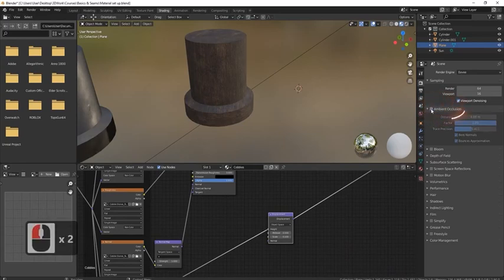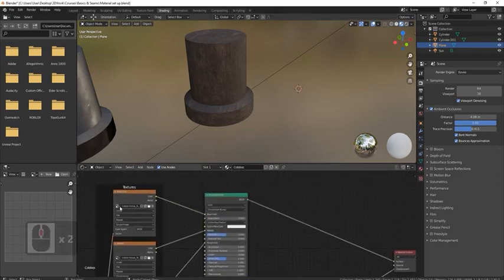When you click this on, you can see already that we really get much more shading on here, much more realism and things like that. Now, as I said, you can get textures where they have ambient occlusion already built in, but I find actually doing it this way generally gives you a better result. Now, the other thing you can do is you can mess around with the ambient occlusion and really bring it up or down, mess around with factors and things like that, and really get kind of the shadows that you really want on the surface of your actual object.